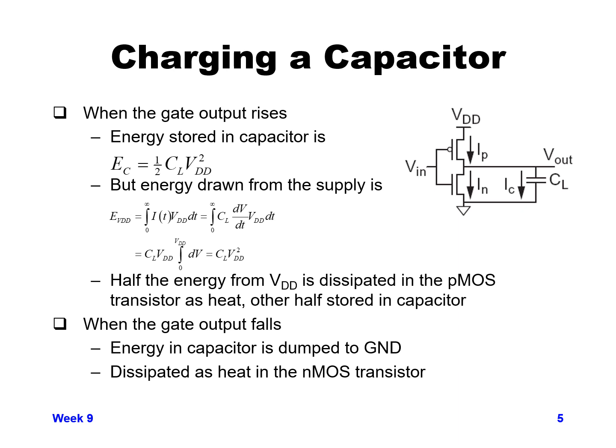So the second half of the energy is dissipated as you're discharging the capacitor back down to 0 volts. Charging up and discharging the capacitor, that full loop consumes CV squared in terms of total energy, but only half of it gets dissipated as you're charging, and the other half gets dissipated as you're discharging it.